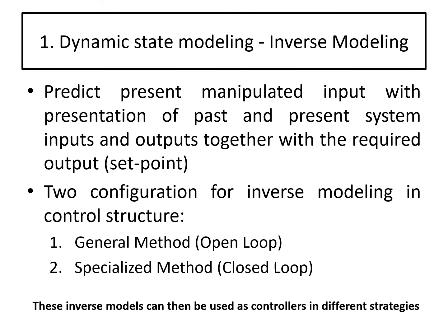The perfect inverse model is the controller itself. What we want is the set point. What is the controller input or manipulated input that we need to get out to the process to give us the set point? So definitely it's a perfect controller. If you have a perfect inverse model, it's a perfect controller. If not, you'll have to put some extra touch up or some extra addition point values to make up for the non-perfect inverse model.